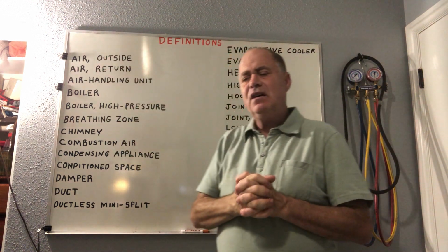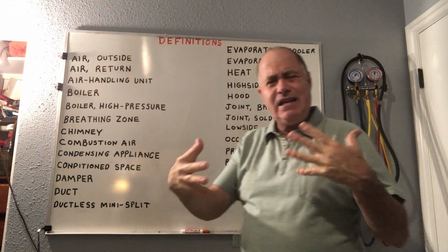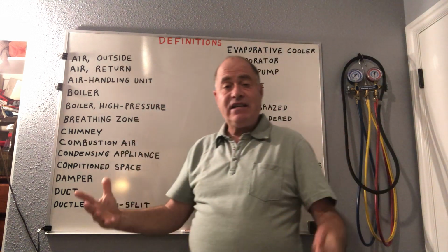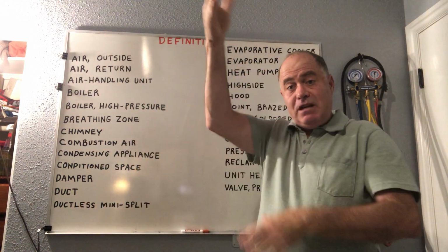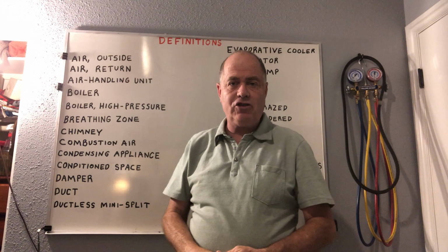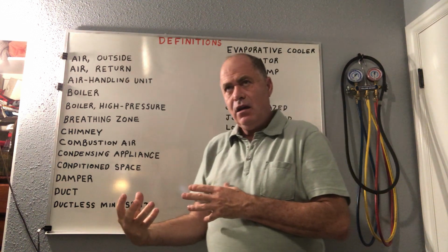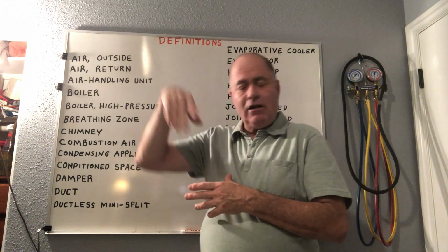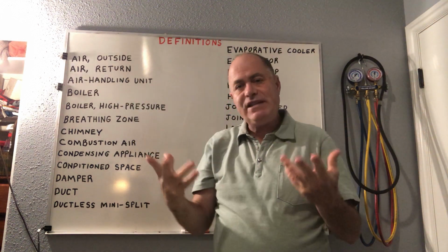Traditional furnaces that you might have in your home are 83, 85% furnaces, and they provide a lot of nice heating, but if you touch the vent or chimney pipe, it's very hot to the touch. So you're paying for that heat, but a good percentage of it's going up out the chimney pipe, out the vent pipe, to outdoors. You're wasting that heat.